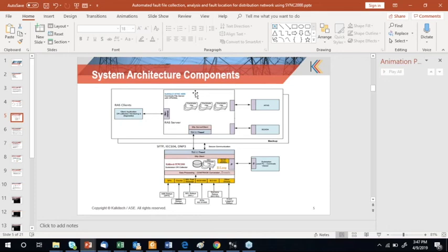Another question is on Z-loop implementation. What is the utility return on investment for Z-loop impedance? So we have a detailed analysis based upon one of our deployments in EDP Portugal, on the distribution side of Portugal. They have feeder protection relays in all the MV substations, and the additional thing they needed was just a Sync 2000 collecting the data, that is the disturbance record file, calculating this loop impedance and providing this data to the central system,